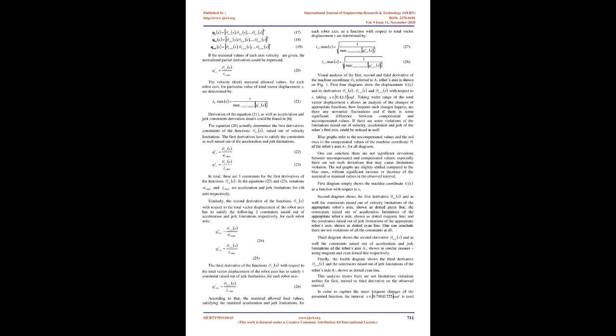3. Derivative analysis of the machine coordinates as a function of total axis displacement. In order to check if some unwanted changes and violation of feed, acceleration, or jerk constraints occur, the array of compensated coordinates vectors is analyzed against the appropriate uncompensated coordinates vectors. A tool path defined as a line in 3D physical space, with a length of approximately 1,500 mm, is the use case analyzed in this research.